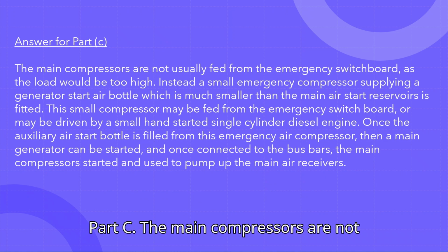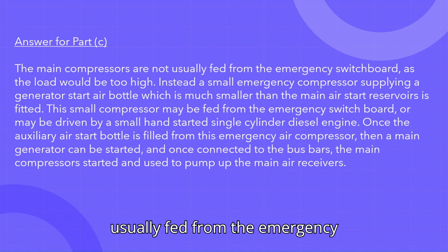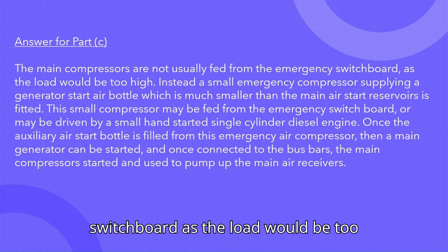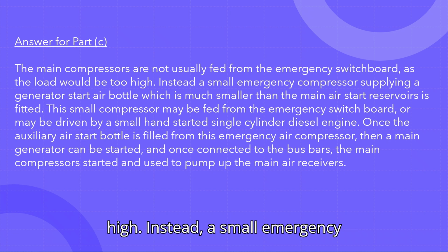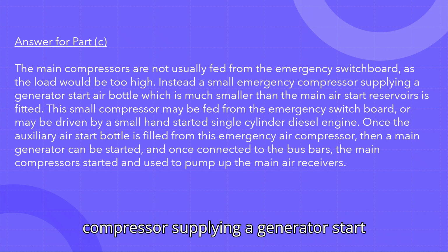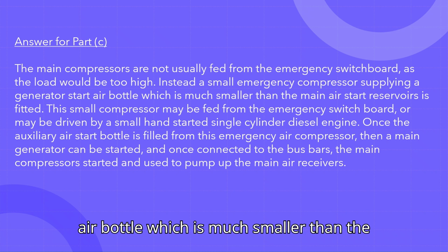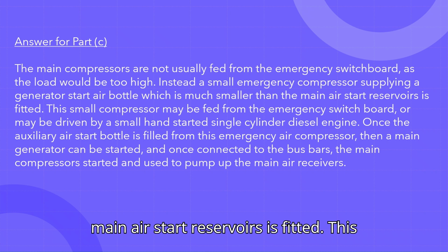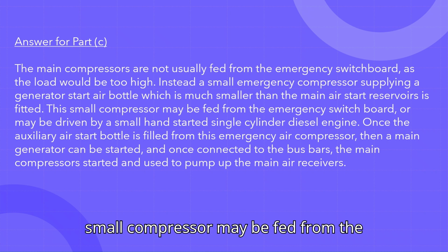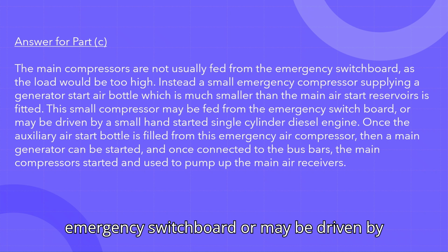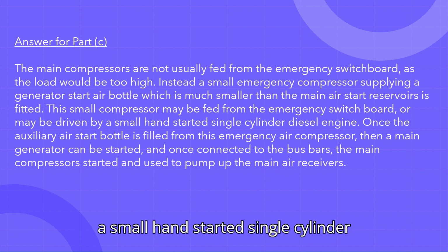Part C. The main compressors are not usually fed from the emergency switchboard, as the load would be too high. Instead, a small emergency compressor supplying a generator start air bottle, which is much smaller than the main air start reservoirs, is fitted. This small compressor may be fed from the emergency switchboard, or may be driven by a small